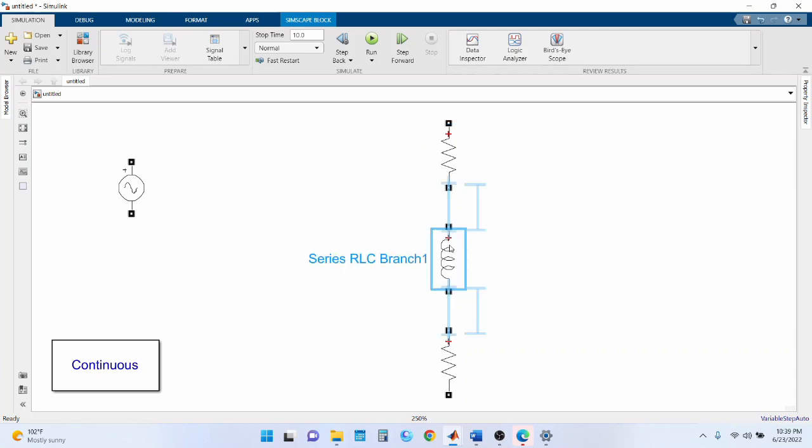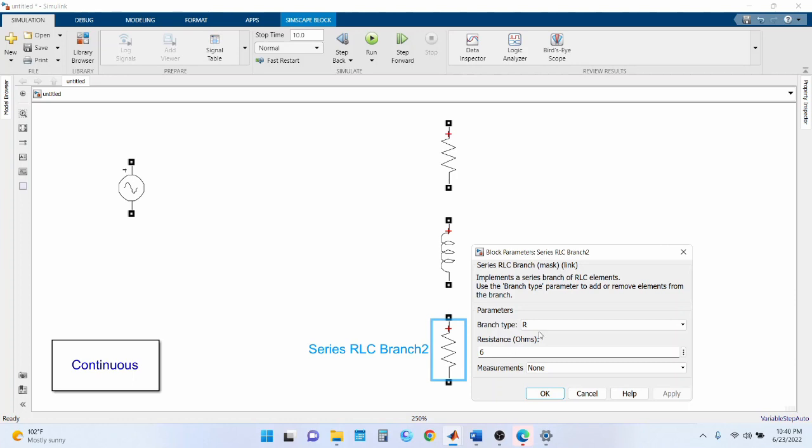So what are the reasons why we need a low inductance? Usually for power systems we have a high inductance, but in small circuits only a small amount of inductance is present because the length of the wire is not so much. That's why we do not usually have too much inductance in small circuits unless we are talking about huge transmission lines, right? So always remember that. If you somehow in the future go to model a transmission line which is kilometers long, you would see that this inductance value is quite high. So usually we initialize with a very low value.